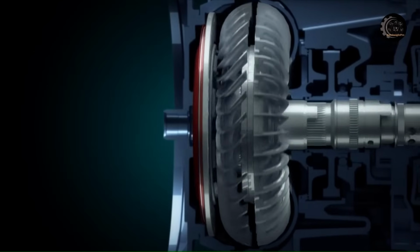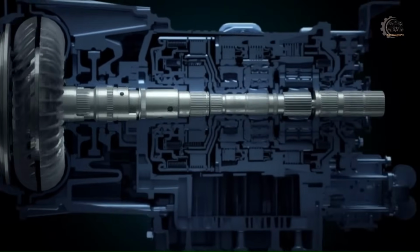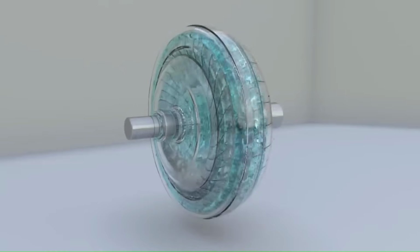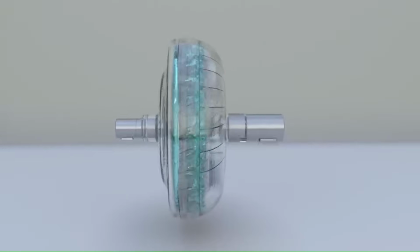At low speeds or when the vehicle is stationary, the turbine may not spin fast enough to match the speed of the impeller, resulting in a condition known as stall. During stall, the torque converter acts as a fluid coupling, allowing the engine to run without stalling while the vehicle remains stationary.